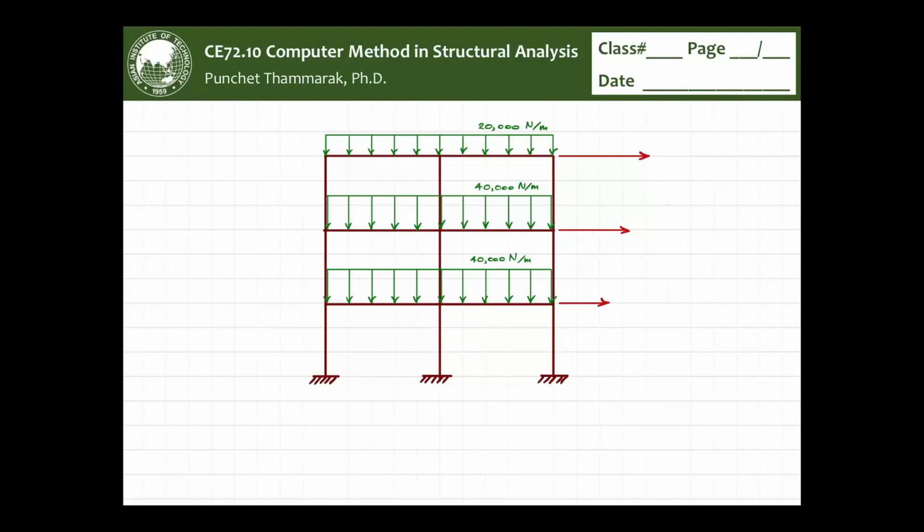And then the earthquake load, if we put like 3% of the weight of the structure, the overall weight. 3%. Okay, so 20 tons divided by 100, you get 0.2, and then multiply by 3. Why is it so small? 3% of the weight. Yeah, it could be just that. So 3% of 20 tons is 0.6 ton, which is 6 kilonewton.